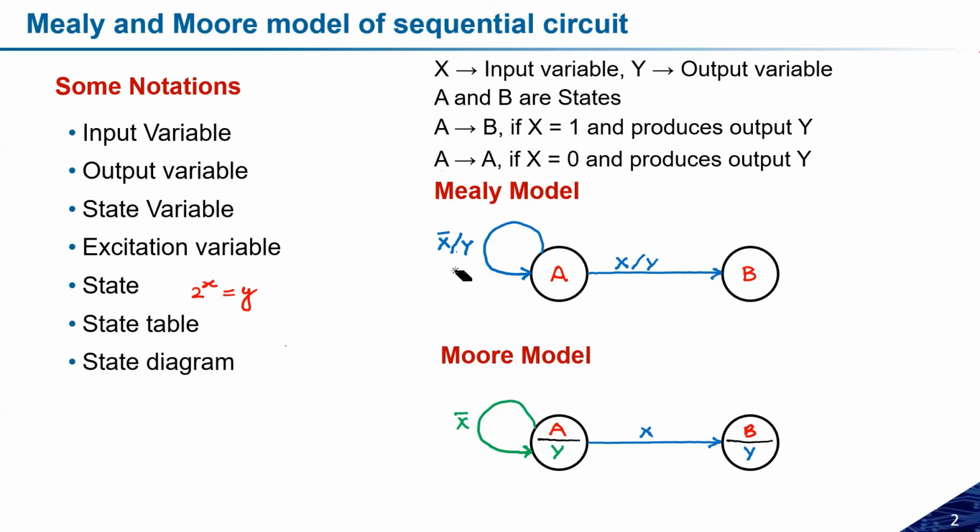One thing that you have to remember in the Moore and the Mealy model is, suppose we are talking about the Moore model, in that case, the output combinational circuit should not depend on the input. And in the Mealy model, the input will also be responsible for generating the output, or simply the output combinational or logic circuit is also a function of the actual input. So this is the only difference that you have to consider.